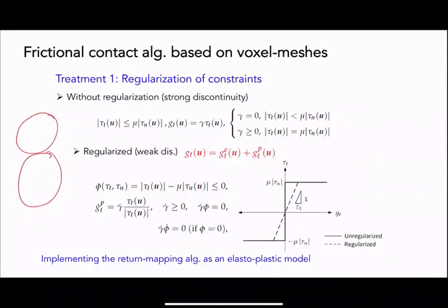As a result, we have the displacement field, which would generate the strain in the background mesh for the bulk. But we also need to use the indicator functions to partition the behavior: in the contact area, we use the contact mechanics and the gap functions to determine the traction response, and in the bulk, we use a classical finite element bulk elasticity material to model the bulk stress field.